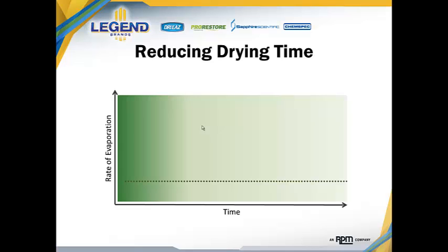If we were to take a look at a drying rate where we were just naturally relying on a dehumidifier in the room without an appropriate amount of airflow, again, the overall drying rate is going to be extremely slow. If we have appropriate airflow in the beginning stages of the job, we have an impact that will reduce the overall drying time by more than half. However, that's only going to get us part way to our goal. Now we've gotten rid of the easy water, which is important. Now we have to tackle the water inside of building materials.